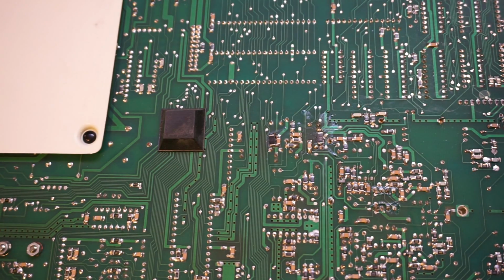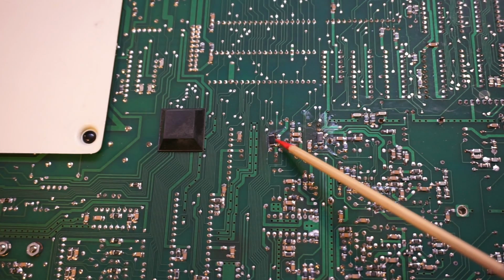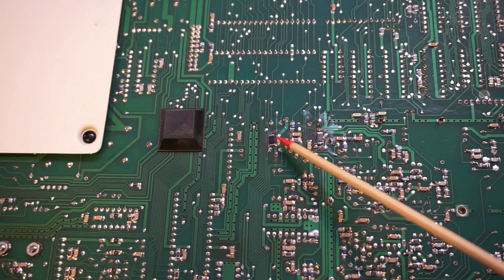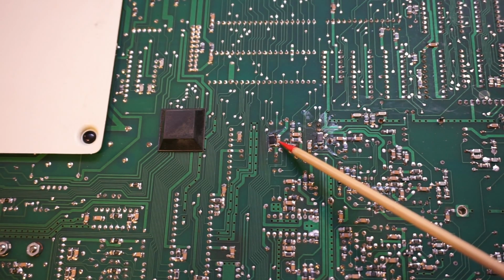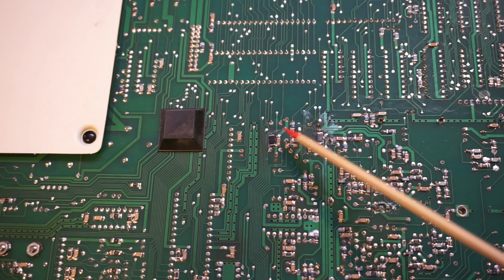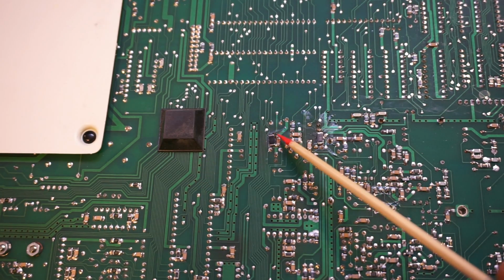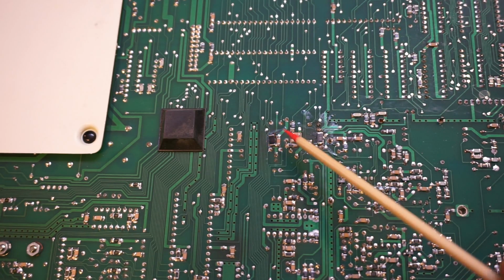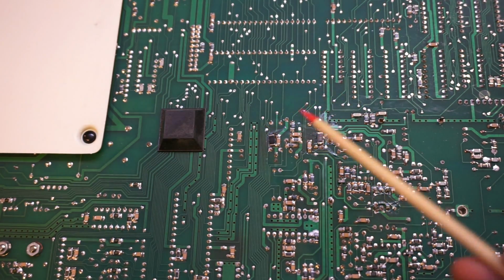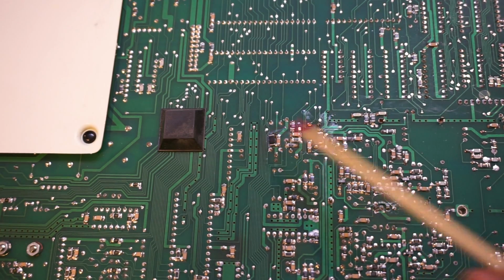So the problem actually turned out to be a little more complicated than what I originally thought. If you recall, we have this resistor that was totally burned, so I replaced it. I don't have a 0402 resistor, which are the ones they used before, but I do have 0603s, and they fit a little bit awkwardly, but nevertheless they do fit onto the original footprint.